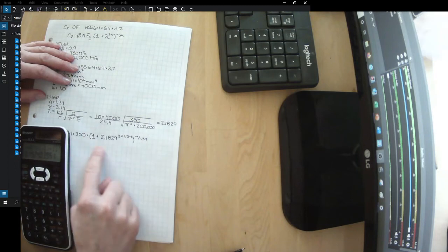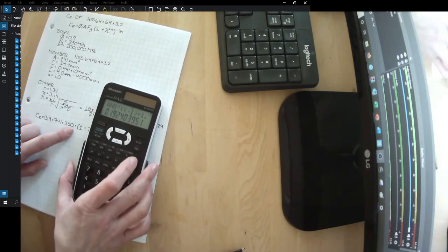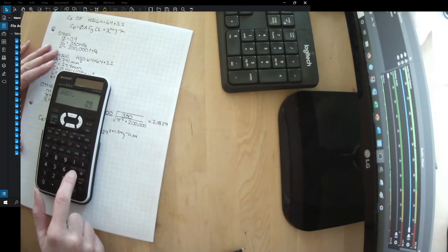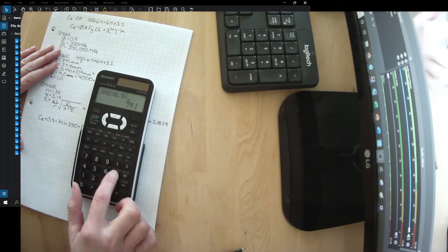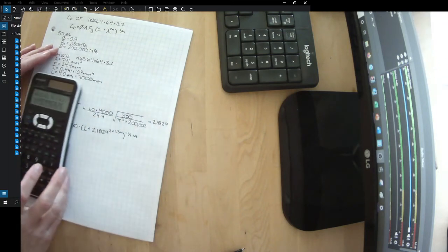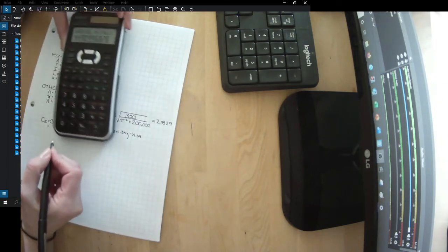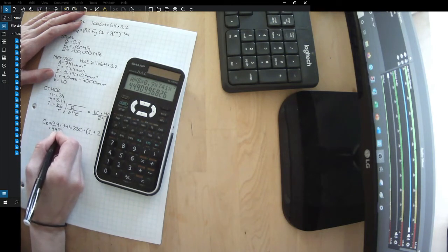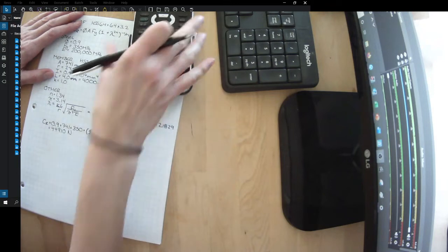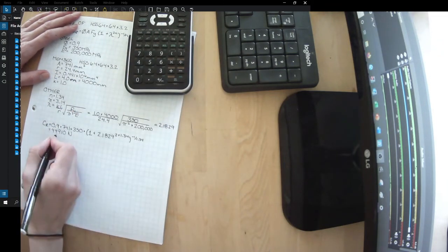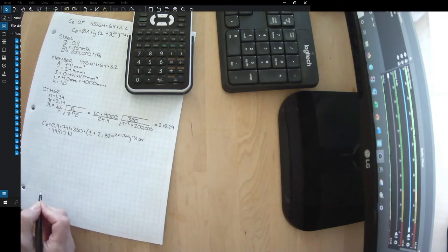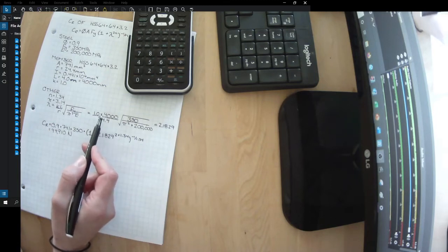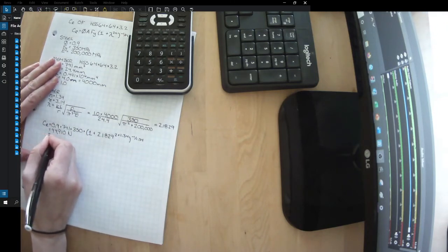So now I've got all of this component done, and then I'm going to multiply all of this times this, or times 0.9 times 741 times 350. We calculate that CR equals 44,910 newtons. Well, once we're in forces, we needed to work in newtons and millimeters because in this equation there was E and stress. But now we can convert this to kilonewtons.